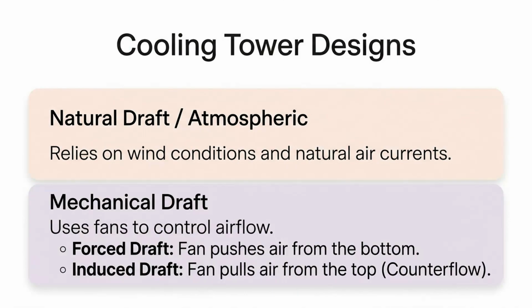Within mechanical draft towers, we have two styles. Forced draft uses a fan at the base to push air in, while induced draft places the fan at the top to pull air up through the falling water, creating a highly efficient counterflow.